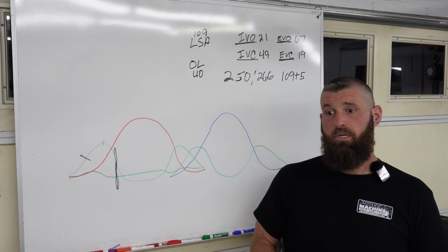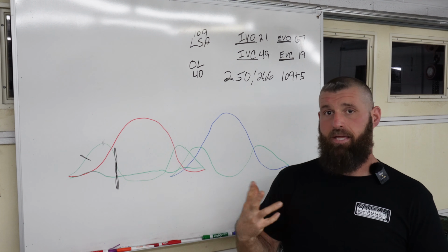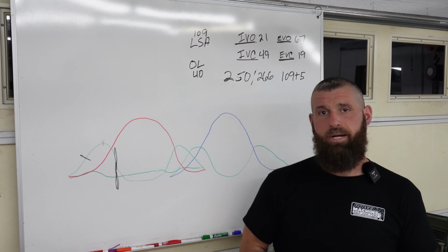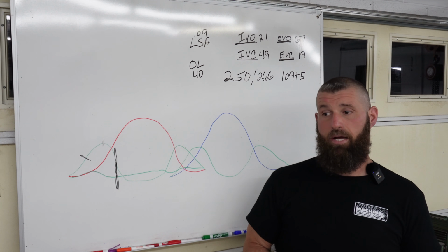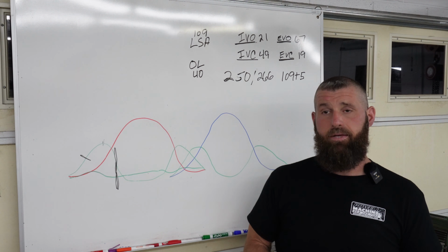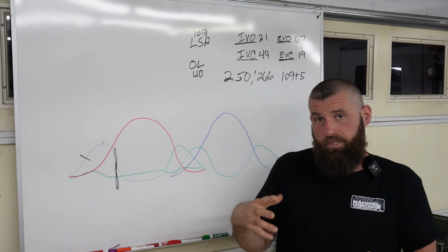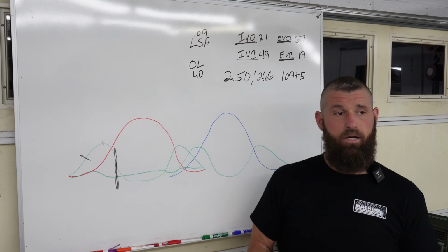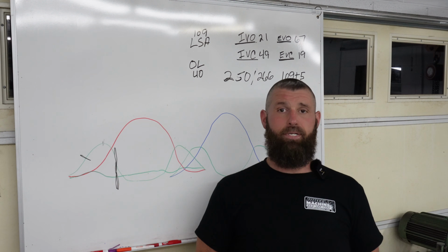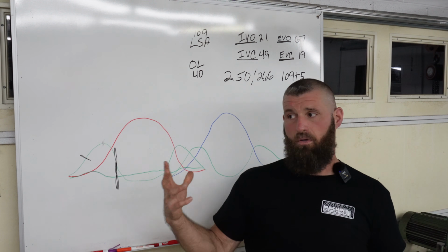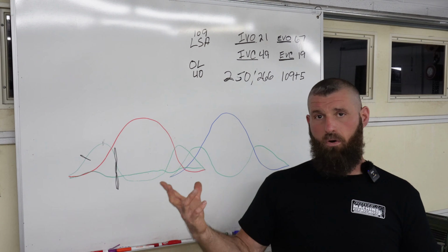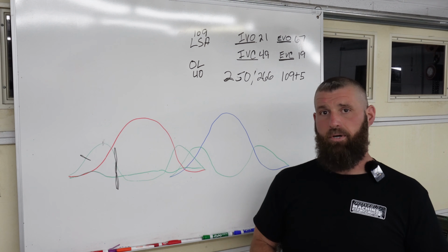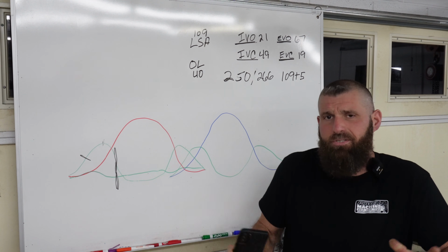But still, most of the time, my cams are smaller than everybody else's. People tell me all the time, man, that cam's way smaller than everybody else said. And the math is the math. So I try to do it with the system we've been using. And 90% of the time it works out great. And the other 10% of the time we just have anomalies that we can't account for, or some data wasn't accurate, or they done did a valve job that knocked 20 horsepower out of the head, and that's why we need more cam. So there's just a lot of variables.